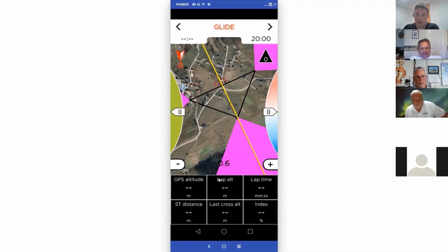So what will this help me when I fly? This comes into account for the last triangles. Basically, every time I finish the lap, I check my lap altitude. That will show me if there is a zero sink, or let's say around zero sink. I know after first lap, I lost 95 meters. Okay. At that time, I immediately know that from 500 meters, there will be no way I can do 6 laps, but I can do 5. So my tactic is then to go 5 laps.